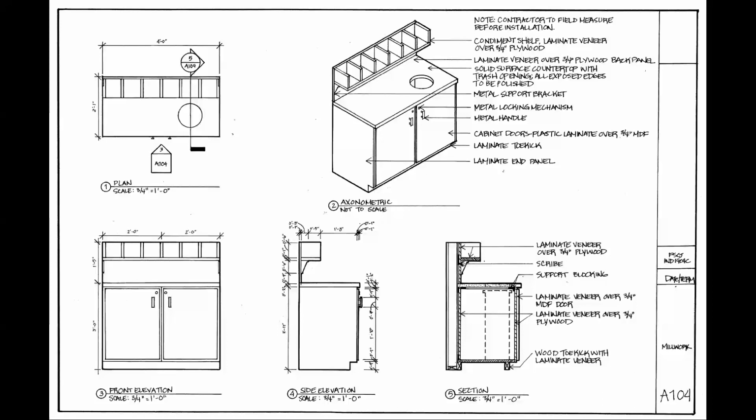The second reason is because if something were to change on this drawing set, we don't want to have to guess or hope or search through an entire set to make sure that we've caught the changes in all the places that we see it. Ideally, we want to show the information in one place, one time, so that if it changes, we know if we change it in one spot, we got it everywhere. So that's why information was chosen and shown on specific drawings.